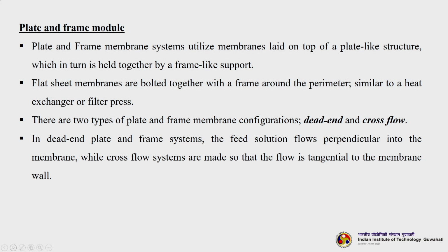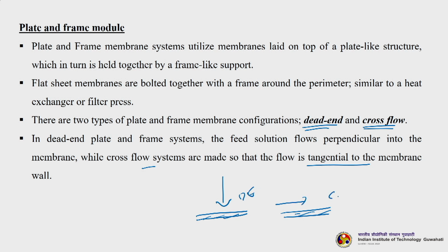There are two types of plate and frame module configuration possible, one is dead end, another is cross flow. In a dead end plate and frame system, the feed solution flows perpendicular to the membrane, whereas in cross flow systems it is tangential. This we have known. This is how the feed flows in dead end, this is the membrane, and this is how it happens in cross flow.